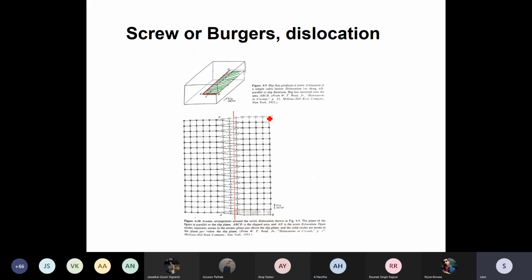Have a spiral notebook. Through the spiral, through the center, along the axis of this spiral, put a pencil or pen in. That's your dislocation line, that pencil or pen. And on the surface of that spiral, you have the atoms lying there, and they are off from their equilibrium position. So the atoms are arranged lying on an imaginary spiral. Some below, some on the page of the paper, some above the plane of the paper. So this red color thing is the imaginary line around which the atoms are lying on an imaginary spiral.